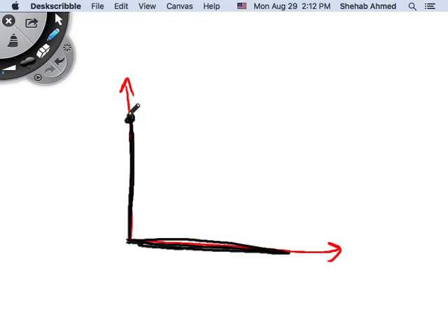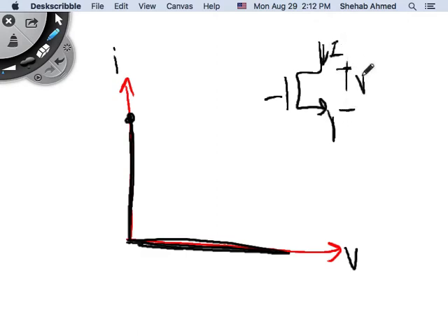So, this is the current to the device, this is the voltage across the device. We typically say that the voltage is 0 when the device is turned on, and I can push a lot of current equal to ID, my rated current, for example. And when the device is off, I can block a huge amount of voltage equal to a certain value of VDS rated across the device. It's a good approximation of this. Instead of here, it was something like this, right? Fine. We typically approximate, and this approximation is for the ideal device, right?